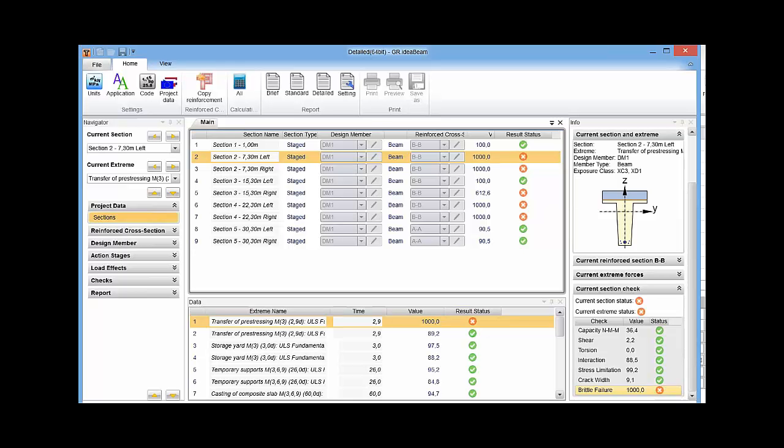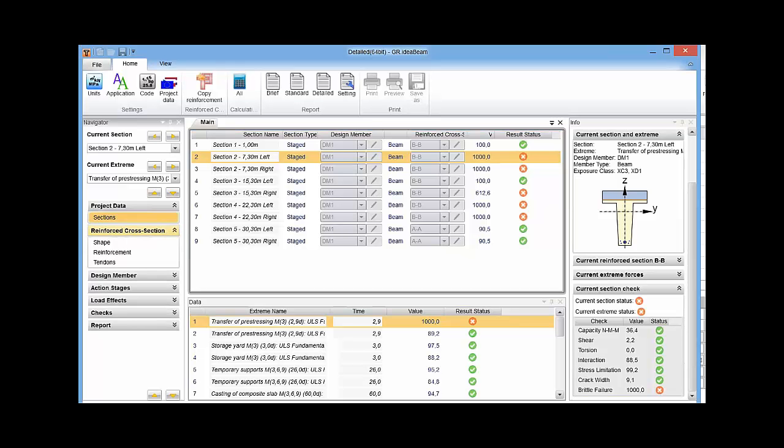Of course it is a problem because we have no non-prestressed reinforcement, so any tension here must be transferred by the reinforcement. So if we don't have Eurocode for bridges, then this check will disappear. We will not check it because it's not required strictly according to the other Eurocode. So we should now make or define some reinforcement.